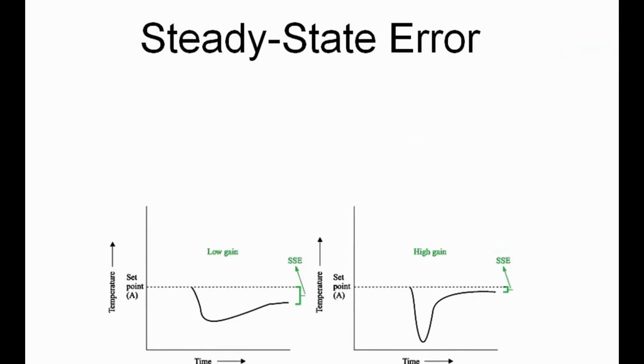The whole idea of control is that there's to be an error, and we've got to solve the error to reach the set point. But as we begin correcting the error, it is harder and harder to detect the actual error and harder to amplify it. And so the result is that an error always remains, and this is called the offset or steady state error.